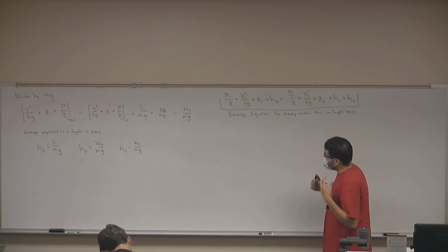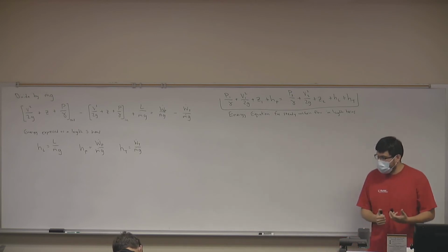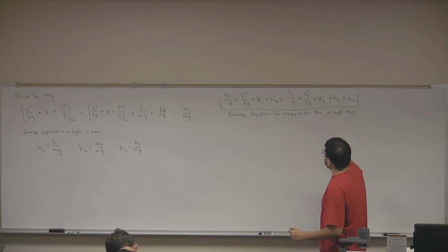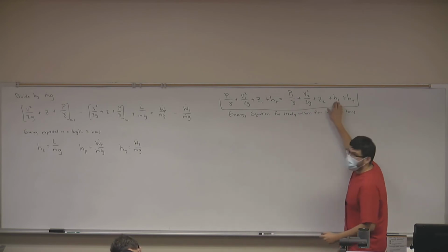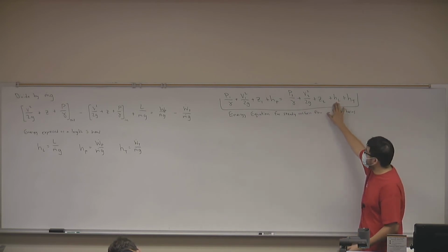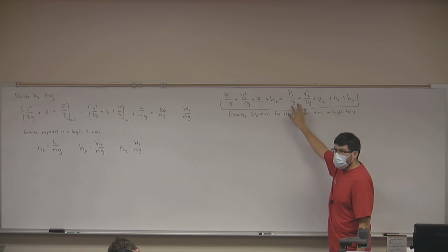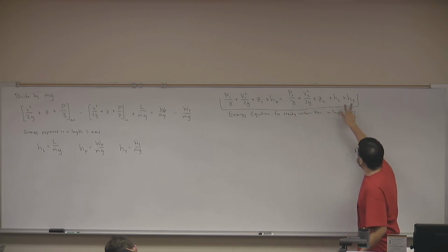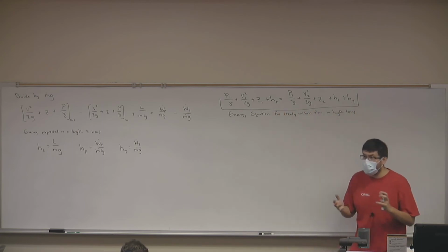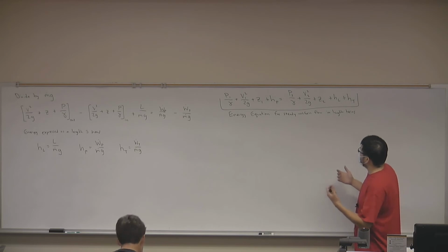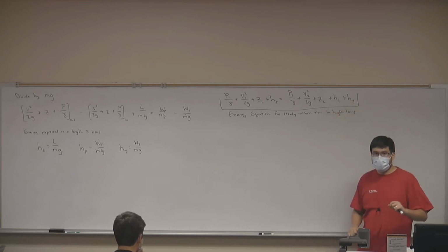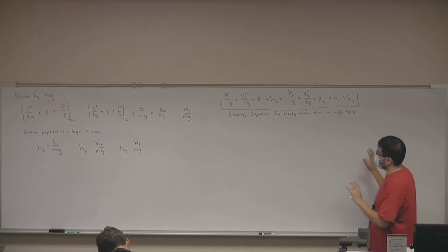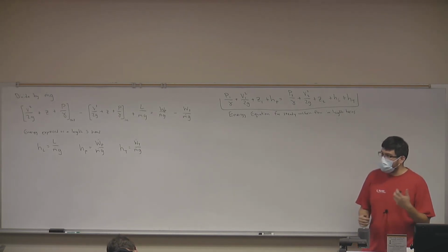Notice that when you talk about energy, you normally don't include pressure, right? Energy is kinetic, potential, and internal. So where did my internal terms go? Well, my internal terms are part of my loss, okay? And why do we get this pressure term? Because this pressure term comes from my work. So my pressure terms and my pump and turbine heads are part of my work rates. My heat transfer rate and my internal energy are part of my head losses. So as long as you understand where all those terms went, you should be able to reconcile this equation with what you learned in your thermodynamics class.